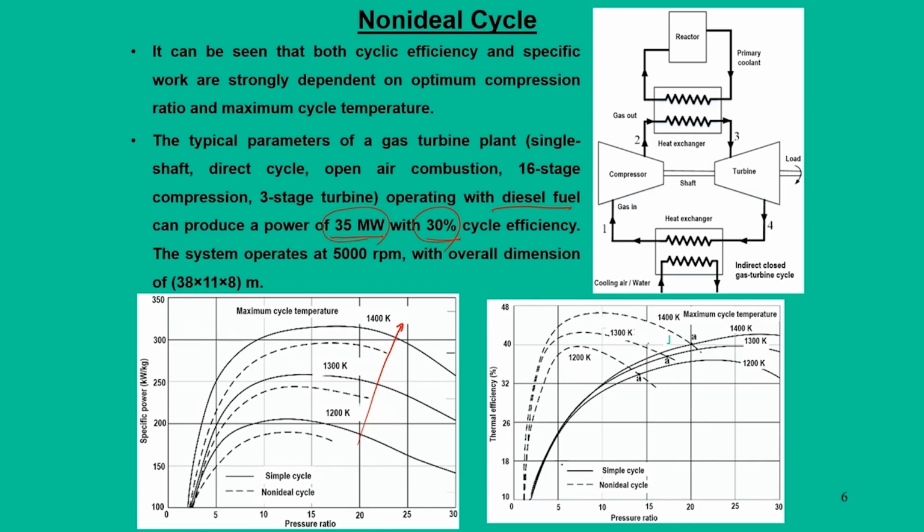The cycle efficiency also gets fixed, but one interesting observation here is that for ideal cycles these curves are continuous and only dependent on the pressure ratio, whereas for non-ideal cycles various efficiency terms come into the picture. Due to these reasons, a continuous, monotonic increase of thermal efficiency or work output is not seen.